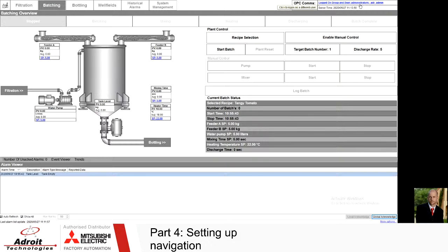And then also our logged on user. You'll also note, guys, that I'm also quite a fan of tooltips. So hovering over an object gives our operator a little bit more information around what happens when he clicks on that. It's very important for those. So tooltips, very underutilized within our navigation structure. And then obviously I want my operator to be able to see at all times whether his comms to his device is healthy or not. So currently I've got a good healthy comms there.